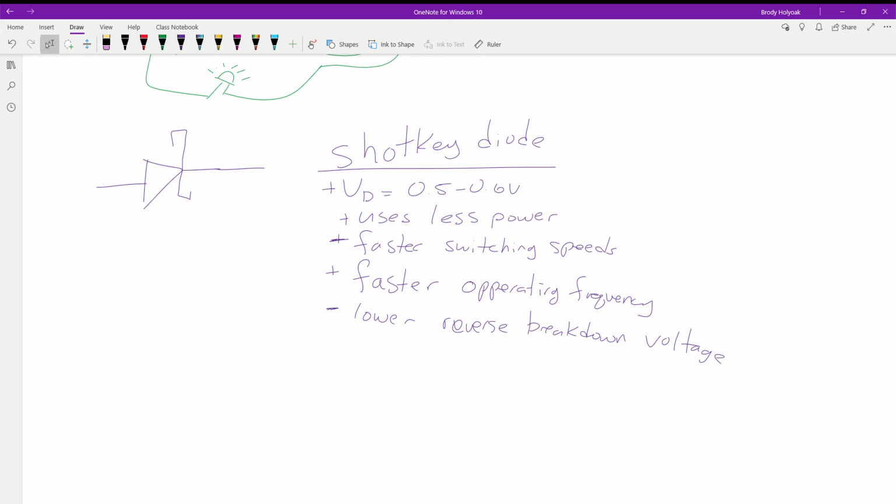Because it's going to start pushing current through when we want it off. It's going to allow current to flow, which is bad because usually we use them in motors, and we don't want power going to the forward coils of motors when you're going in reverse. It'll stall your motor out and then burn it up.